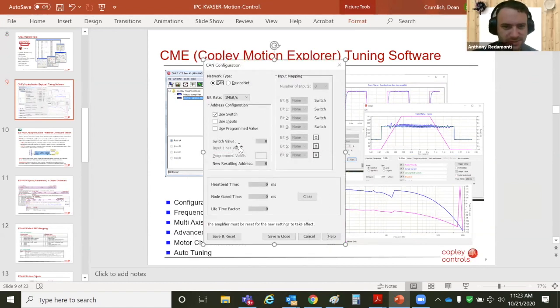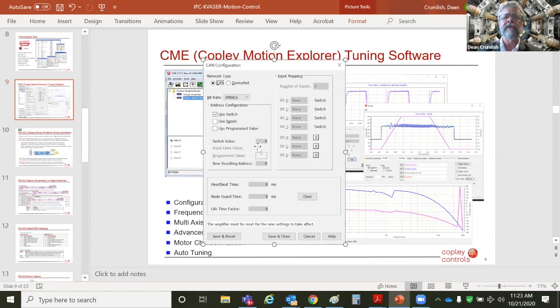Sorry, I was answering some questions. So you want to make sure that the node ID is non-zero. And why is that? Why doesn't 0 work? I think it's part of the protocol that you have to have a non-zero node ID, and they all have to be different. That's a good point. Everybody should be unique. So 0 is not a valid CAN ID. 1 is a valid CAN ID. So 1 through 127, that gives us 127 nodes.